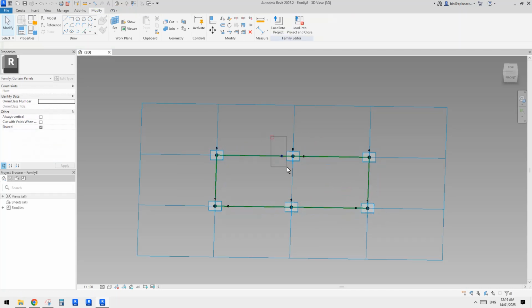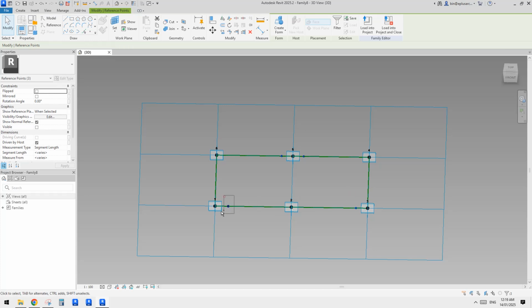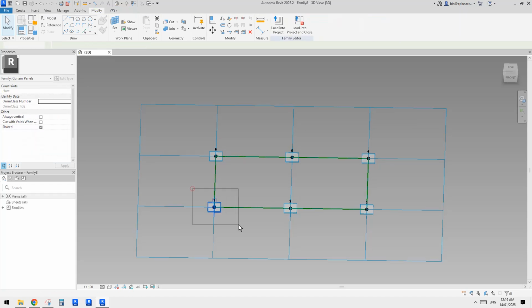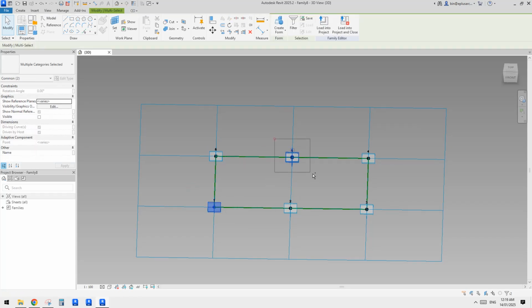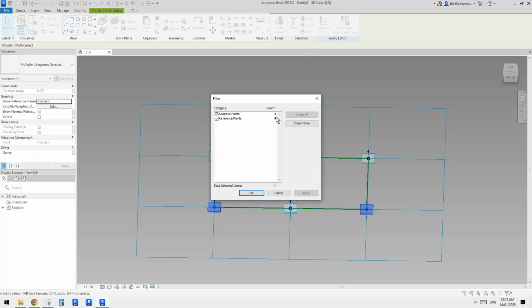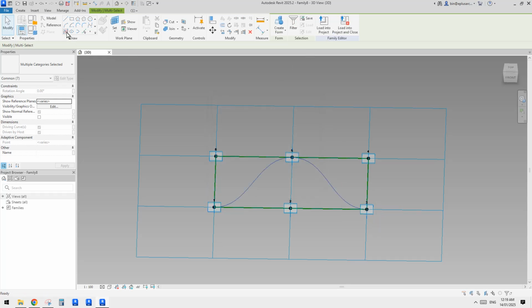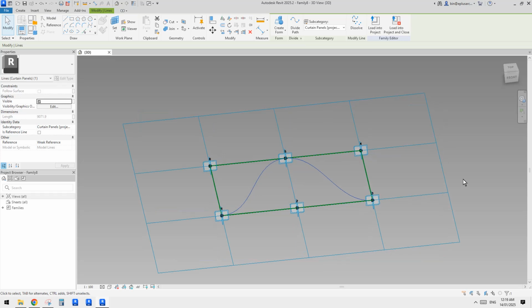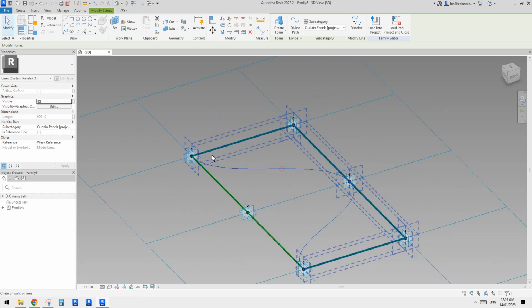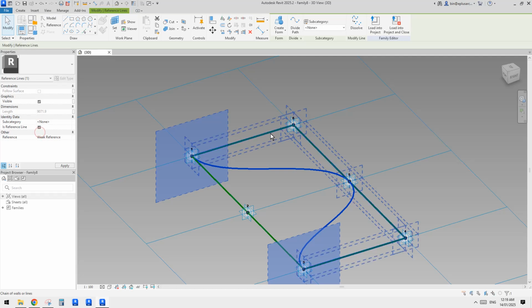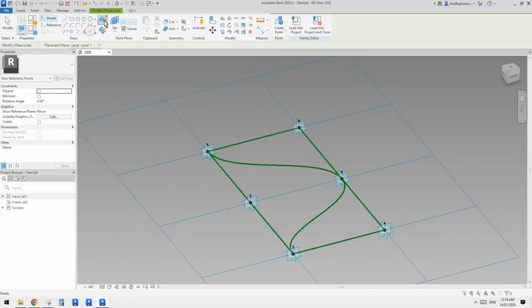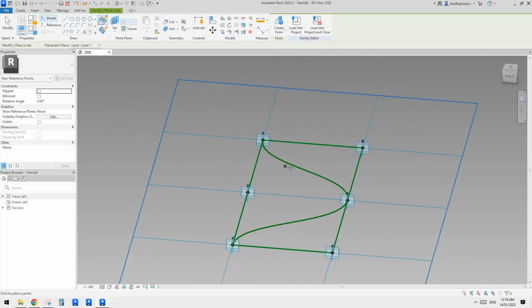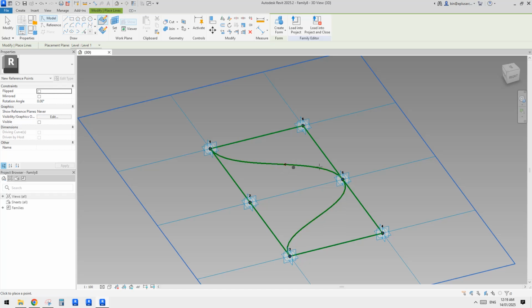So now select all these points and just type in here segment length, maybe just very small, like 1. Now select these 2, control select these 3, and control select these 2. So should be 7 points, right? And then we can create a spline through points. This is the shape we need. Okay, so now we can select this, make a reference line, and then we can select place a point, draw on face, and place onto this, anywhere on this reference line.